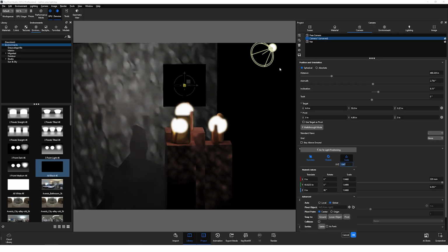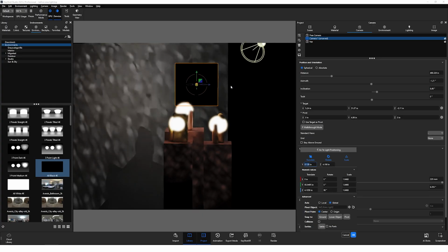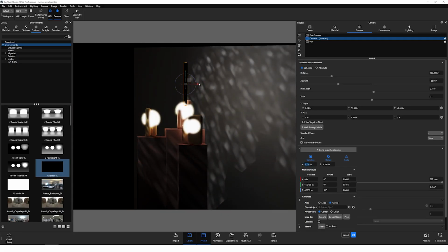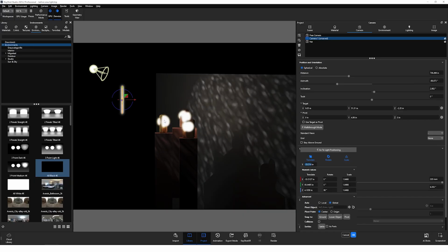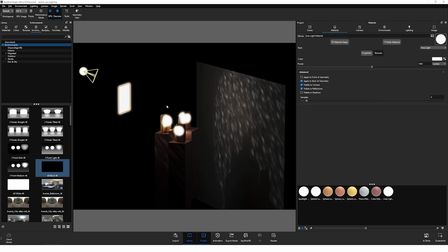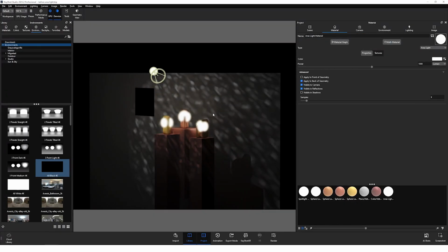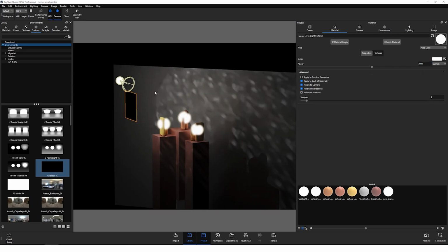As always, tweaking the scale and position of any lights are always going to be part of the process in moving towards a well-done 3D rendering. With a few more adjustments, our area light is now set in place. After double-clicking into the area light to bring up its settings, the next step here is to increase the light's power value. One thing you may be thinking at this point is that this spotlight here is kind of distracting.